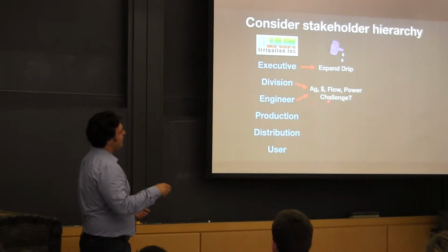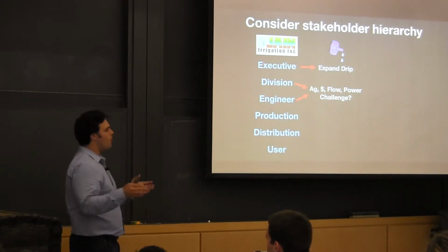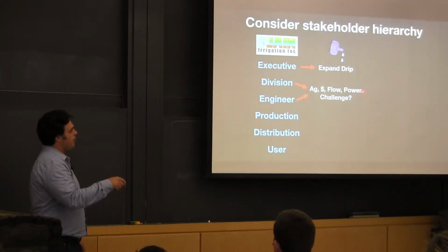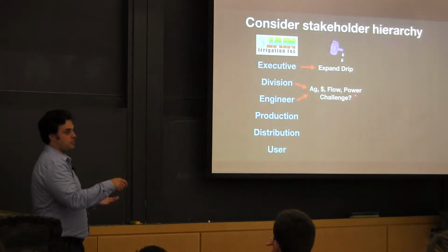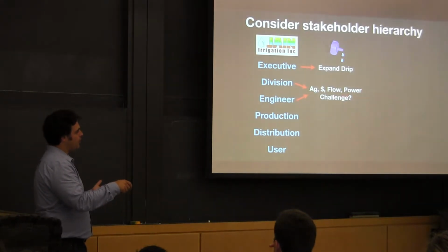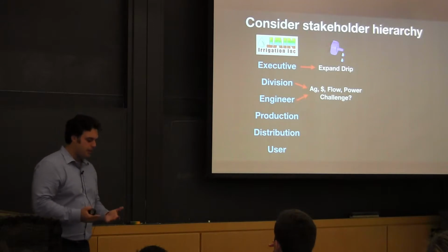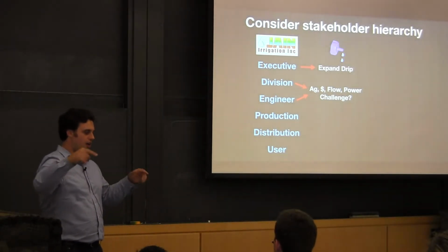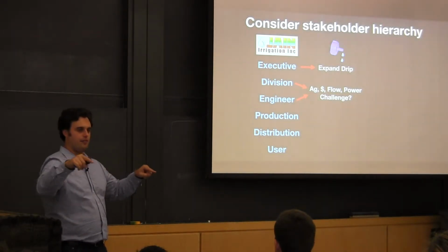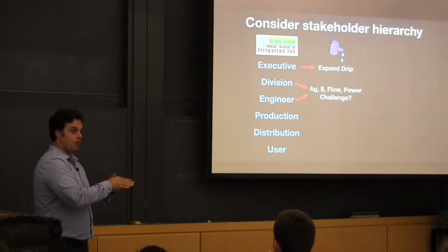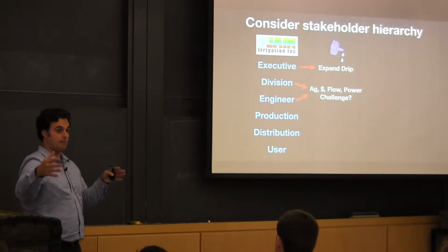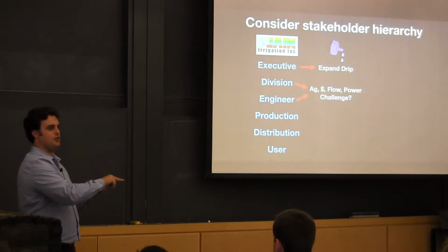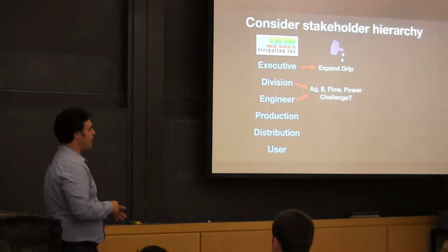So talking with the power and flow guys, I was like, whoa, why do you need so much power to pump the water, right? And the power guys are like, well, you need that much power, so our system's really expensive. You need about 1 horsepower per acre. And then the flow guys said, well, we need to pump at a high pressure so we can maintain a relatively uniform pressure down the line so we get even flow rate out of each dripper. Because as you start pumping at lower pressure, your pressure drop down the line becomes relatively big compared to your pumping head. So you may get like 1/10 the pressure at the end as you do up at the pump. And then your water flow rates are all off.